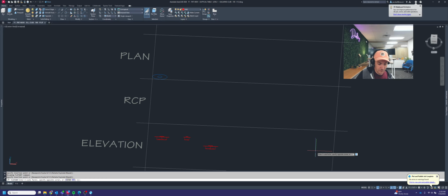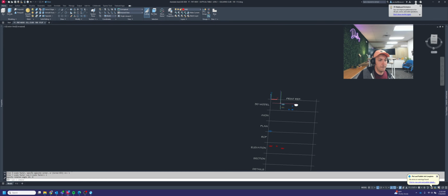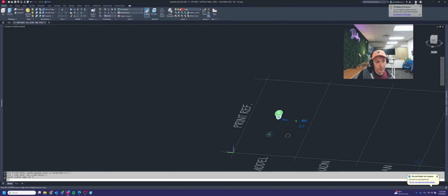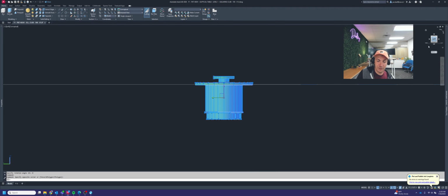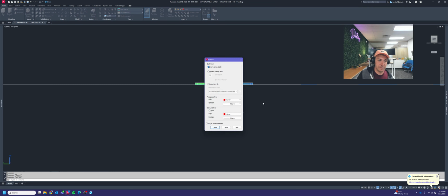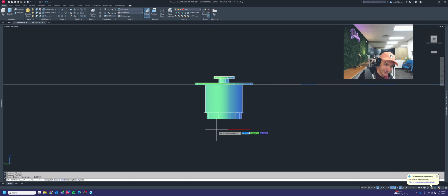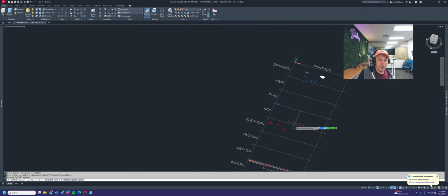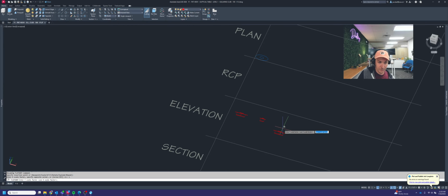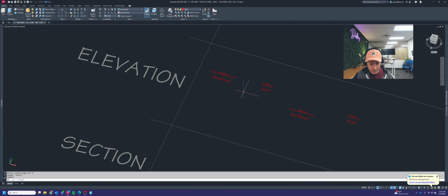Here we go. And we'll do one more flat shot of this side. Just make sure that you're lined up. Using your view cube is a good technique to be able to line things up just perfect, straight on the side of your drawing. Once you make your view, hold down shift middle mouse, and we're going to bring it on over here. 1, 1, and 0 again. And then we're going to line all of these up, explode them, and set everything to by layer.